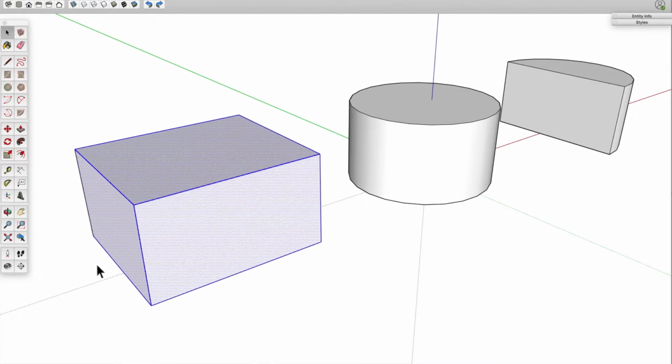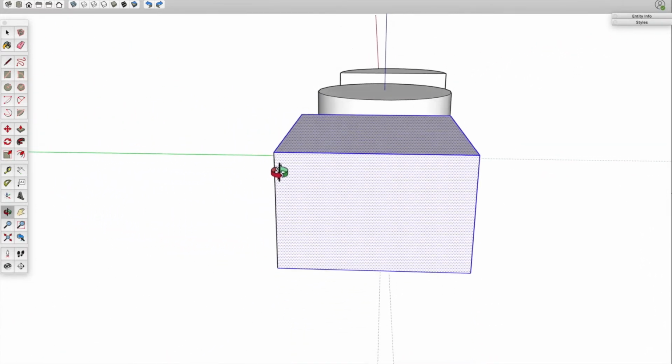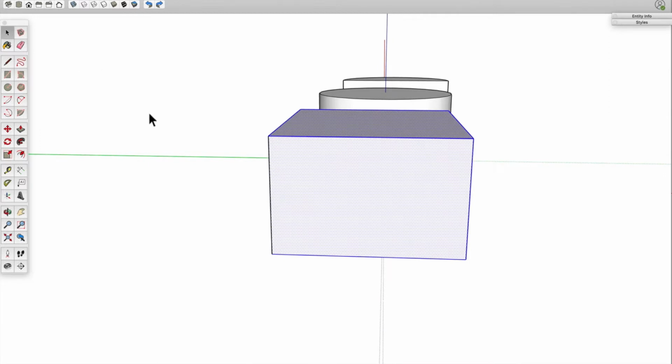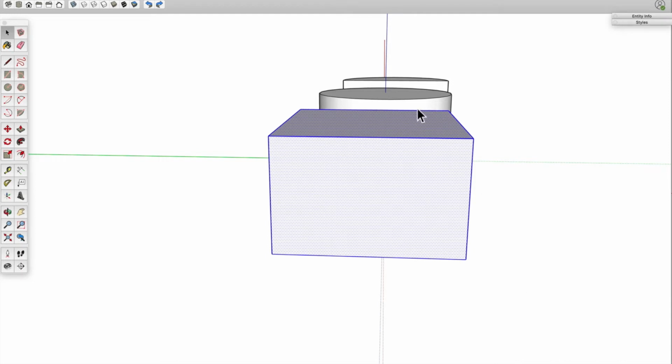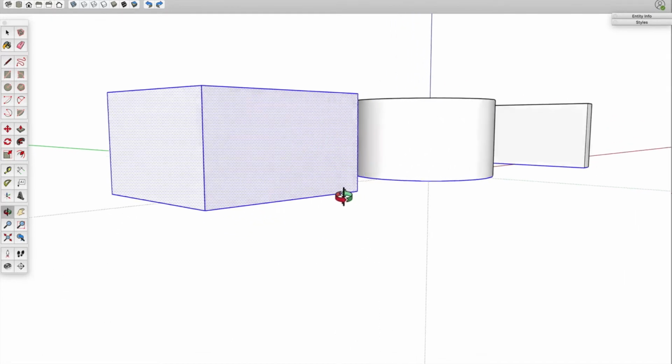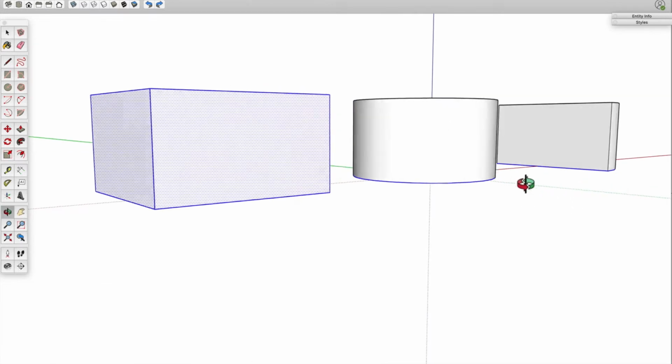Just one thing to be careful about: if you orbit around to a view where you have those other objects in the background, and you go to select, say, just this box, if you drag a selection window around the box, at first, from this angle of view, you might think that you didn't get anything else back there. Nothing looks selected on those half cylinder and full cylinders. But if you orbit around, you'll notice those bottom edges got selected, or in your case, maybe some other stuff.